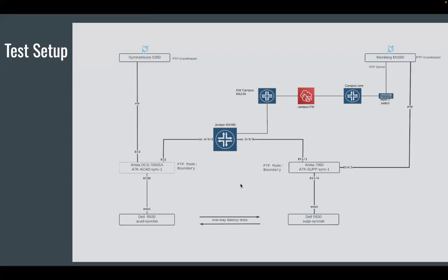Yes, do most of these appliances for PTP support the entire set of GNSS constellations, or are they tunable to just GPS or Galileo or GLONASS or whatever? That is very hardware specific. When we bought the Meinberg, we bought the GPS 180 card, which is just the US constellation, more formally called US Navstar.